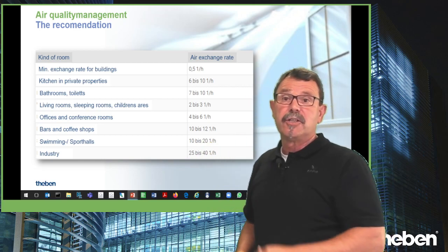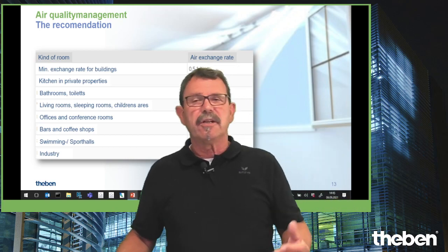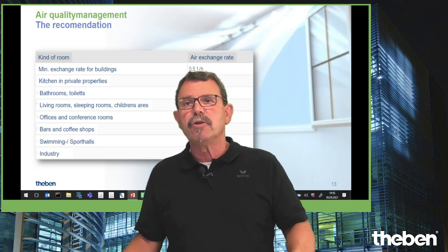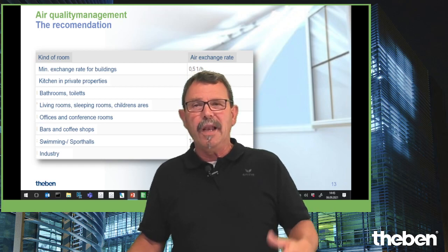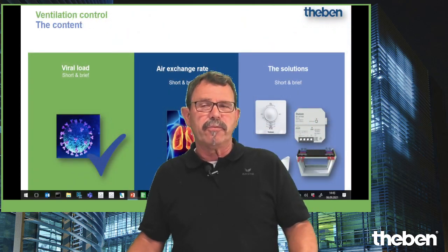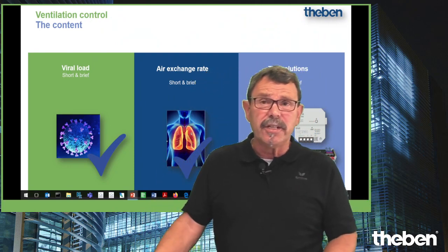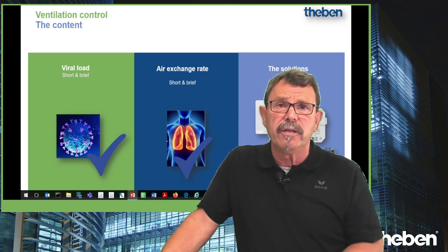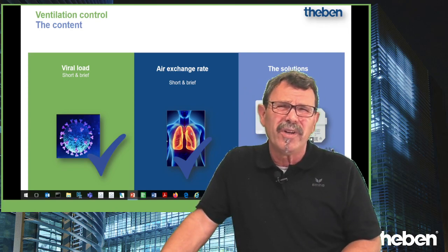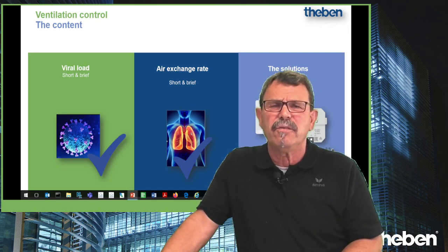So probably 25 up to 40 times per hour, the entire volume of the air has to be exchanged to keep the people well attended, however. So there's a natural regulation, and this has to be cared about. And imagine now, someone tells you to care about the ventilation: open the window when you feel like it. I think during the normal working process it doesn't make any sense, and it will definitely not work.